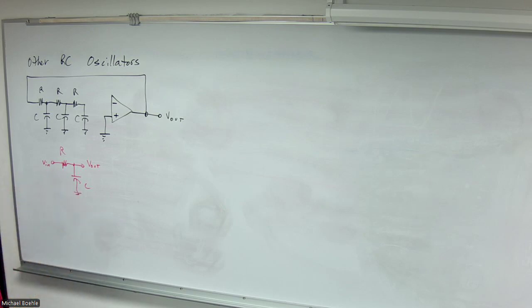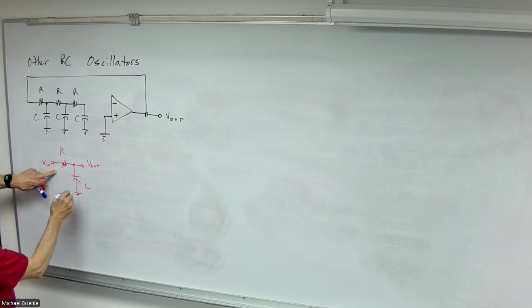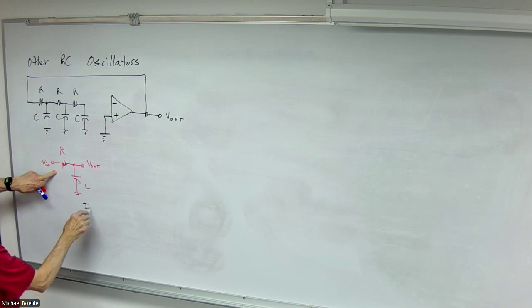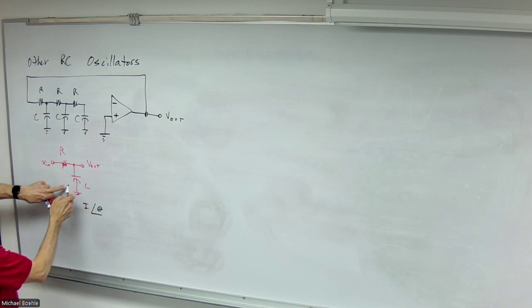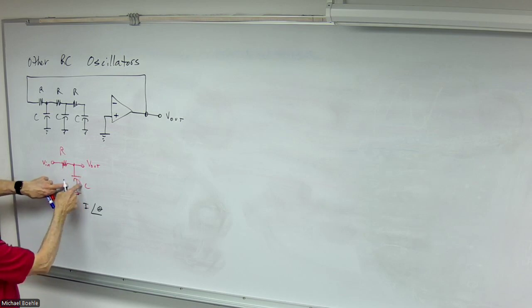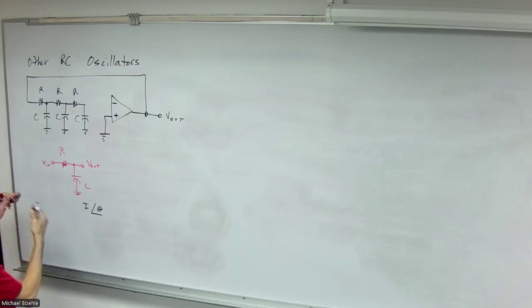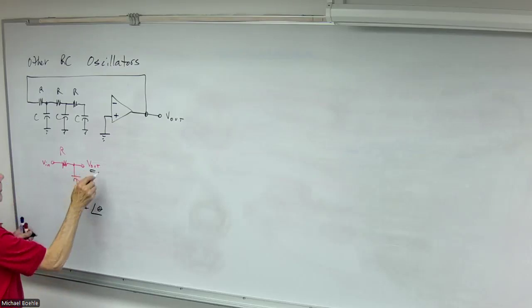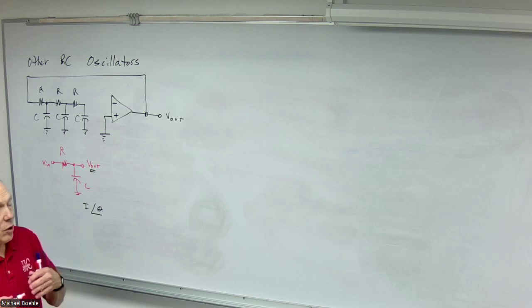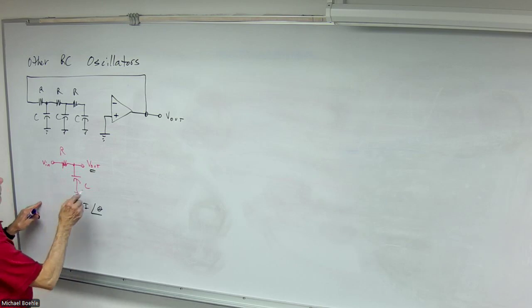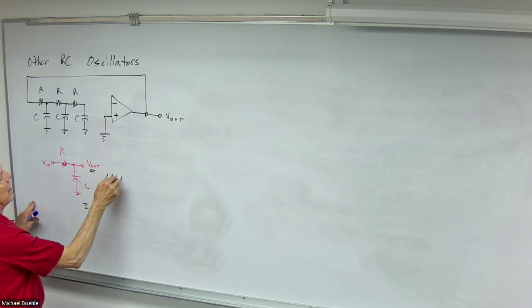Now, the phase shift for a circuit like this is basically what we're looking at is, we're going to have a current that becomes leading. So we're going to end up with some angle of leading current. And then we end up with taking that current across a capacitor that causes a phase shift between the current and the voltage. And since I ultimately want the voltage out, what this is going to do is create a lagging output.